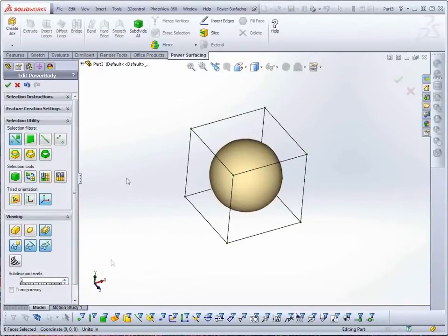Let's go ahead and move the mouse over the cage and model. As the cursor passes over the various elements or sub-objects, they are highlighted orange. In the Select Any mode, the default, you can select vertices, edges, or faces by picking the highlighted element. The selected elements will become blue.